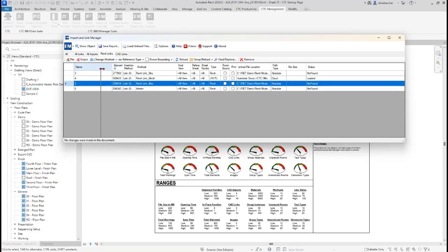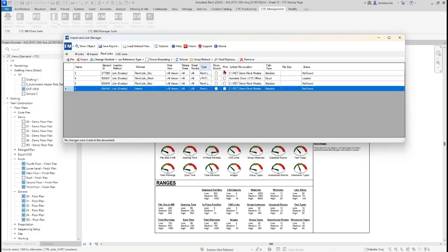Okay, we're dealing with Revit files, so those can only be linked in, which is good, unless you import it in as a group, and that's completely different, or converted it to a group, for example. But we have some additional tools that may be more beneficial, like reloading from the cloud. I might be starting a new project, and I've just saved my model to the cloud. I've saved these, and my consultants or the subcontractors have their files up there. I need to reload those in now.